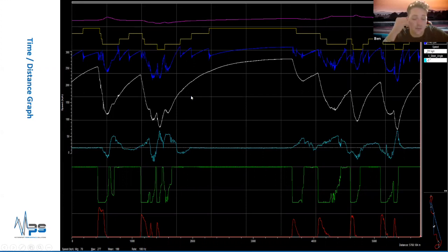Most of them default to what's called auto scale. So it'll go through the data, find the maximum value and the minimum value, and set the display up according to that. Not really an issue in isolation on a lap on its own, but if you were trying to back-to-back compare 2 drivers, obviously there could be significant differences here. So what I tend to do is fix the range in which I view the data myself, so each time you load it up, you know where you are with it, and you're not constantly adjusting your scale to suit the particular data you're looking at.